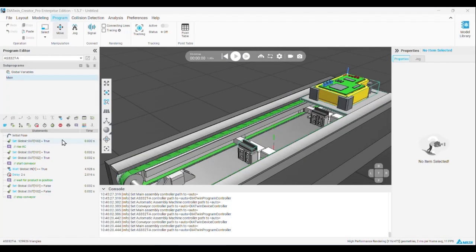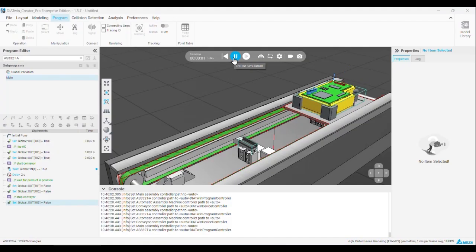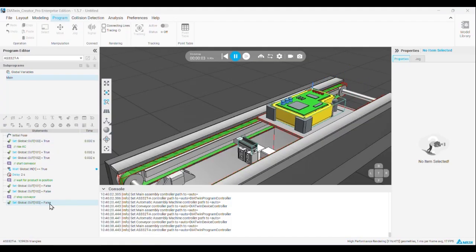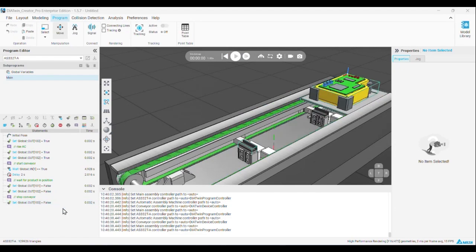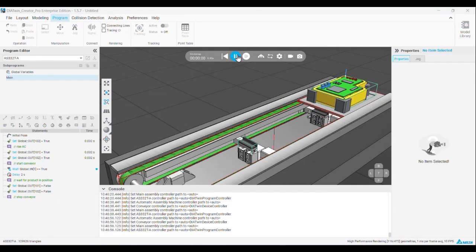You can also write something like, after stopping the conveyor, you can also release the air cylinder like this. We'll make 103 false to make the air cylinder go down. But I think we can first focus on right here.